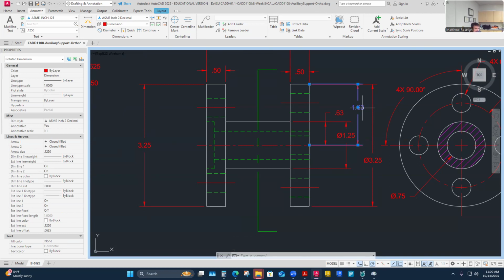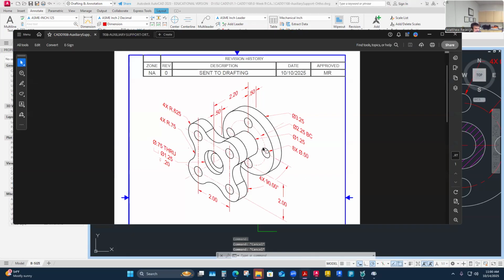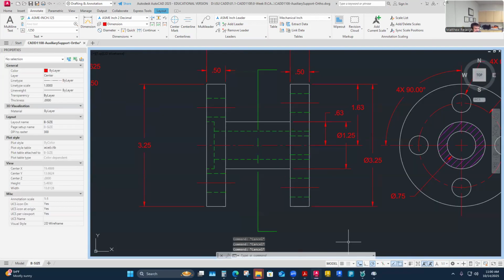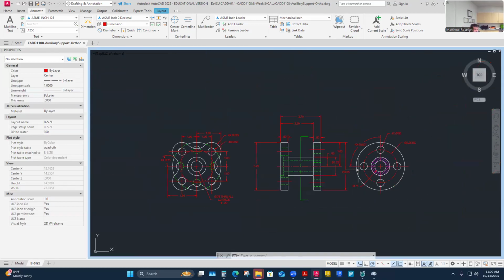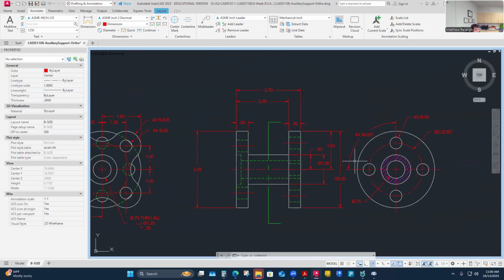So when I'm adding dimensions beyond what was on this sheet, I just have to make sure they make logical sense, that they are half of each other, or else I'm implying that this plate is going to be off-centered. We're talking in the tenths, but that's a lot actually. So if I'm 3.26 to 3.25, that's a big difference. It's only a 100th, but that's a lot. A 100th to a machinist is a mile. So I don't know literally, but in my mind, I think that's a pretty big discrepancy.